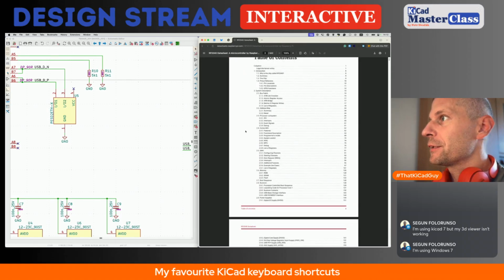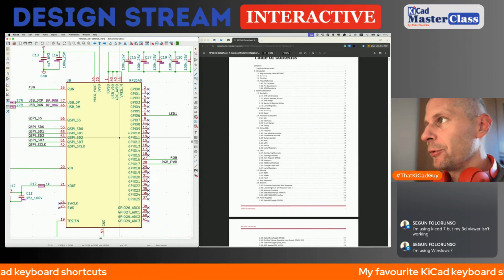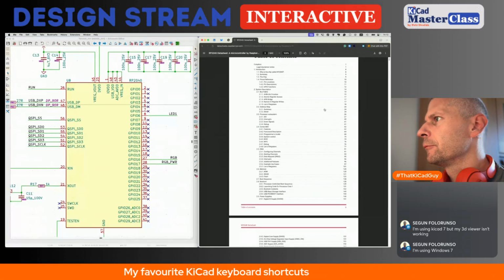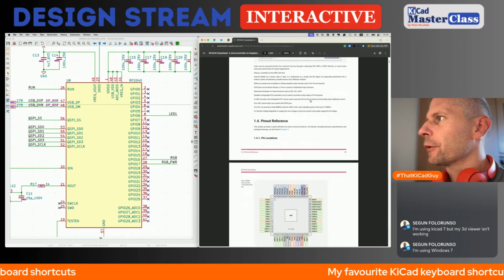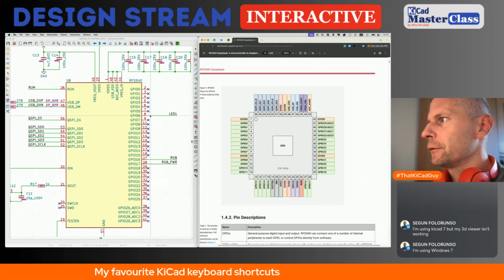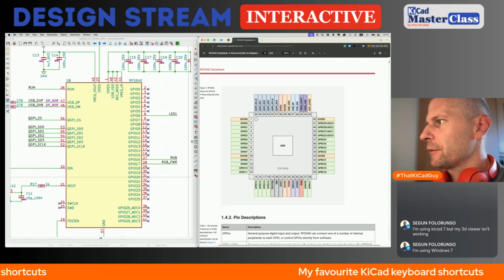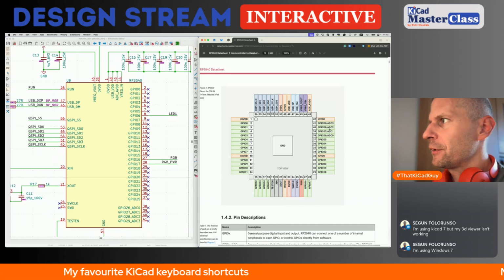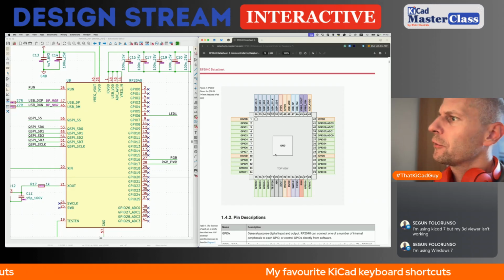So let's check the symbol, and if it works, I just copy the library symbol into my symbol. So here is the pin reference. Doesn't work. So yeah, it seems until 18, then 27 to 25, 27, 38, 41. Yeah, this datasheet should be fine.